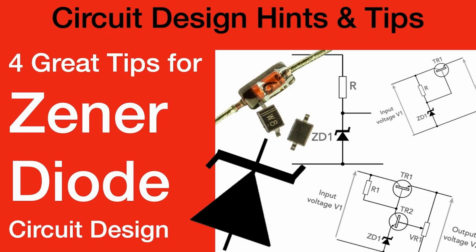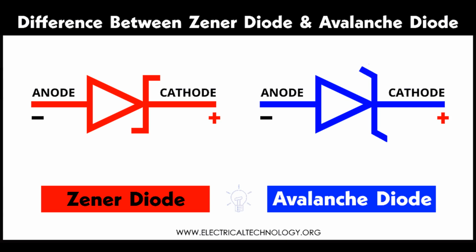4. Voltage regulation. Stabilization. Zener diodes are widely used for voltage regulation because they maintain a nearly constant output voltage despite changes in the input voltage or load conditions. Series resistor. To operate a Zener diode as a voltage regulator, a series resistor is typically used. This resistor limits the current through the Zener diode, ensuring it operates within its safe region.